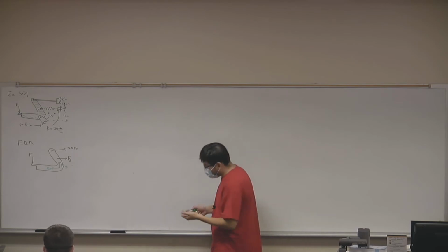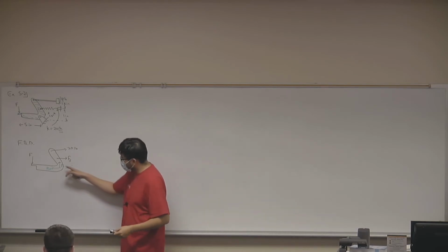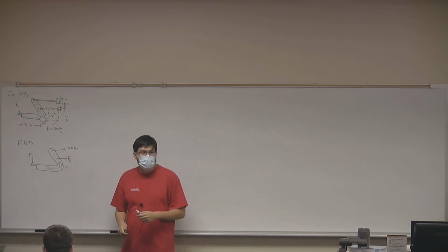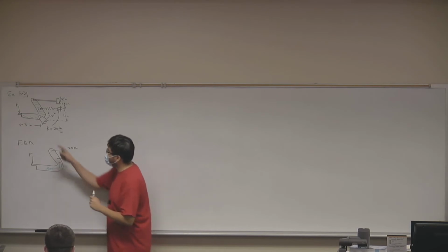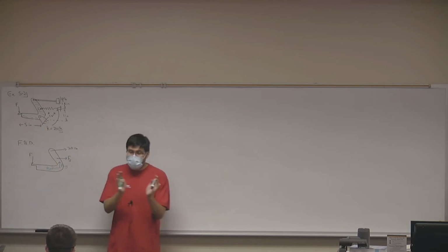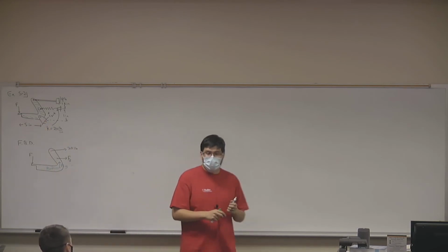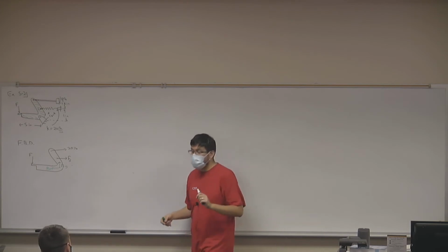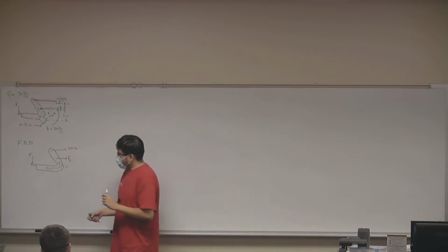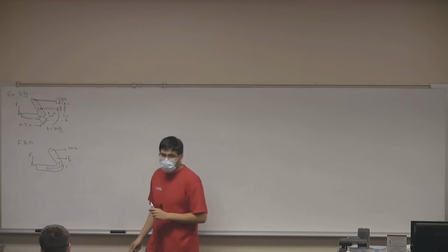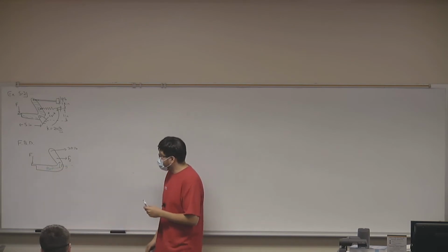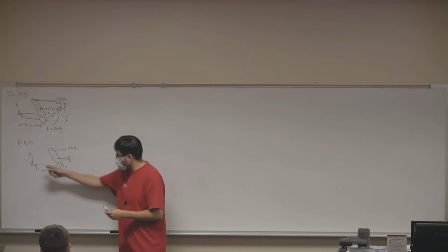Daniel, does the hinge cause or provide a moment reaction? Yes. You want to restate that? Okay, no. Remember, hinges, by definition, don't allow any linear movement, but they allow free rotation. And now my question is, if this system is static, what's this force F equal to? In other words, what's the force that the person pushing on the pedal is applying?